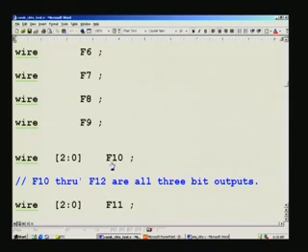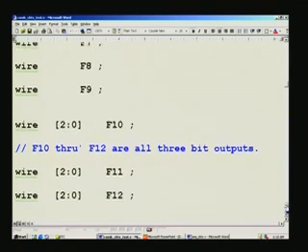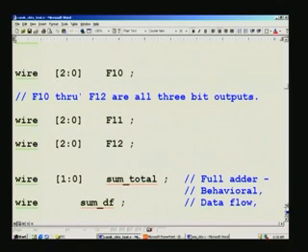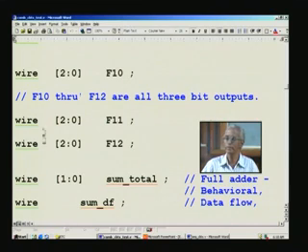And we had some other outputs which are 3 bits in width, and therefore it is mentioned as 2 to 0 here, and all the outputs, or combinational outputs, are wire. So, it is very simple. In a test bench all the inputs are declared as reg, all outputs are declared as wire, right. Note the difference between a design file and this.